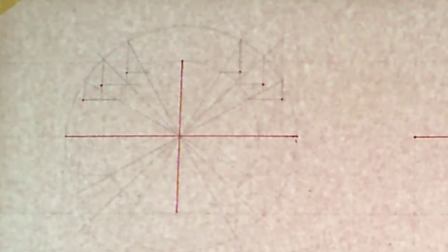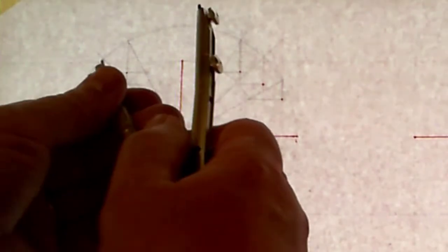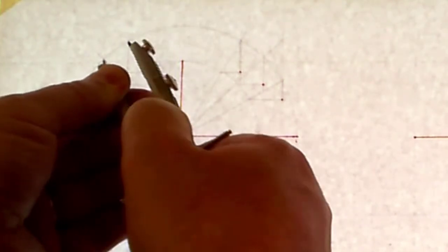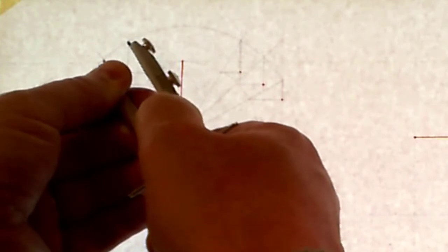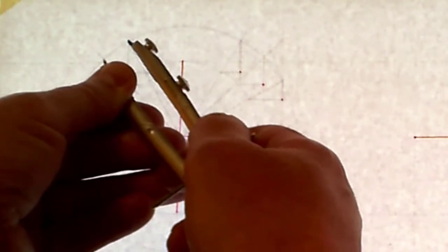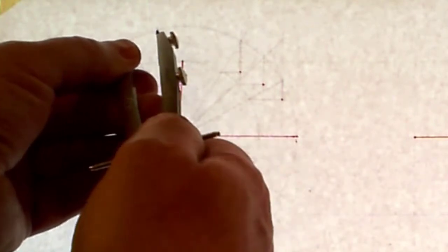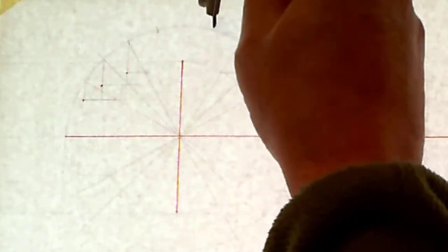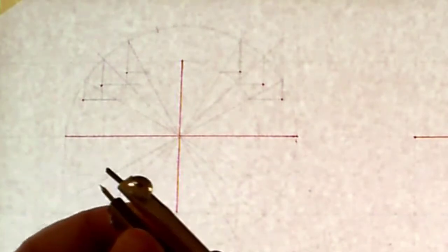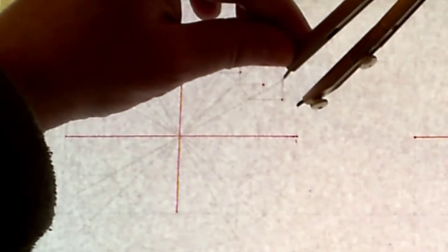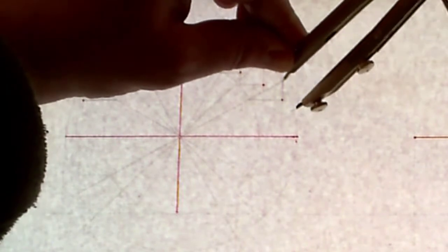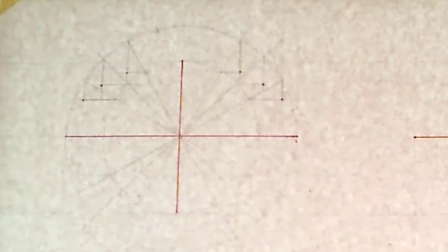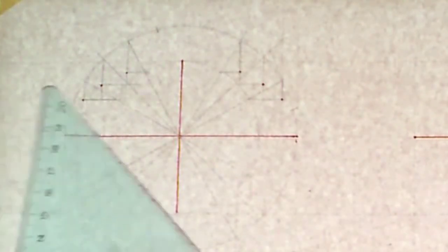So I simply do that by again getting my compass and going to where the distance between the 45 and the 60, or the 45 and the 30 degree line, I simply get one of those lengths there, okay, on the outside here, and I strike that off again, 1, 2 off the 60 degree line here, and likewise on the bottom from the 30 degree line here, the outside of the curve, strike it down and strike it down here as well. Now, what I've established there are basically 15 degree intervals.